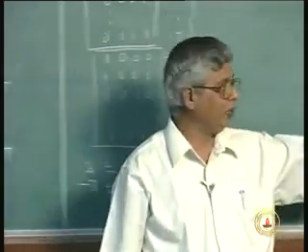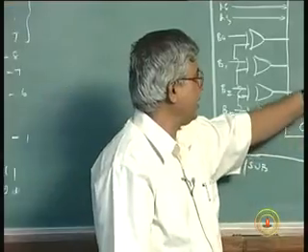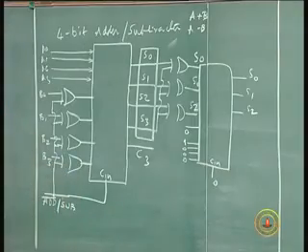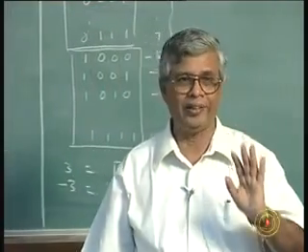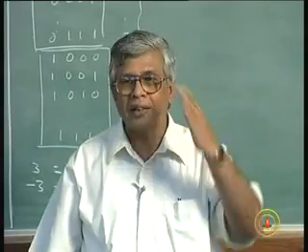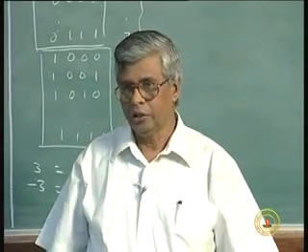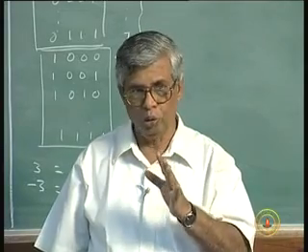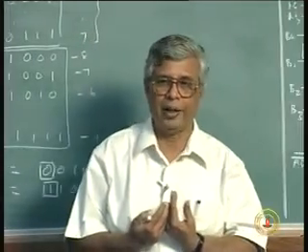If you had a negative number as the output, there are 2 ways of representing it. Either you can represent it as it is, S3, S2, S1, S0 will give you the negative number in 2's complement form. You can keep it as it is, store it as it is, use it as it is in the next stage of addition or subtraction. That is what computers do. Computers do not keep on changing every number to sign magnitude. We are the ones who are interested in sign magnitude.